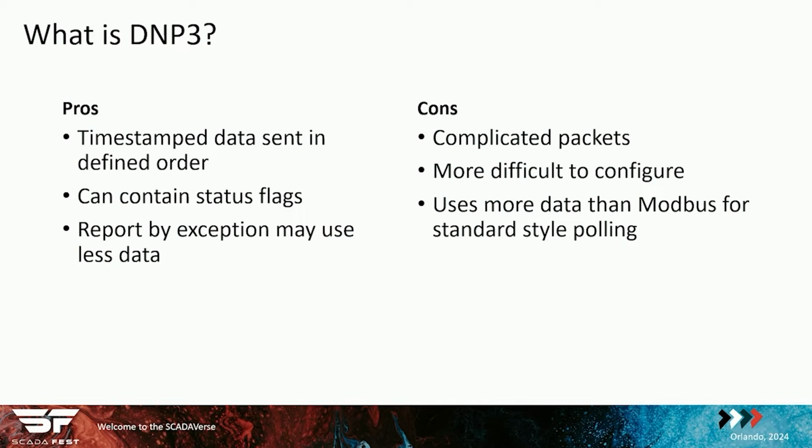And as you'll see, if you do decide to try to use standard style polling, you're going to use a lot more data than what Modbus does to do the same thing. So I'm not saying you can't do it or that you shouldn't do it, because if that's maybe the only way to get the data, that is what it is. But if you have choices, it may not be your best choice.